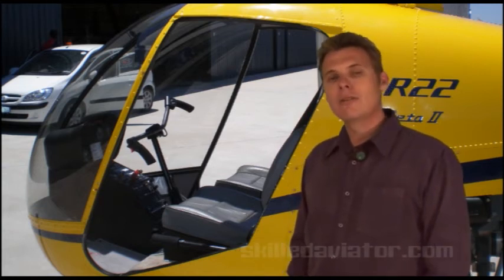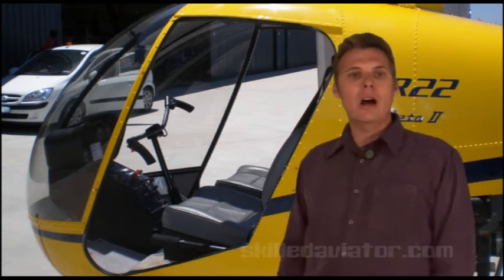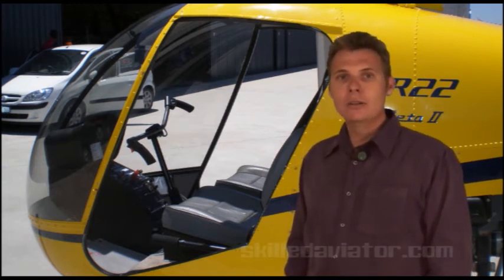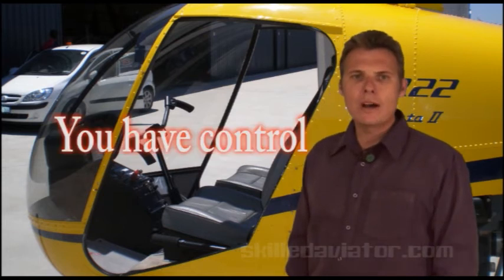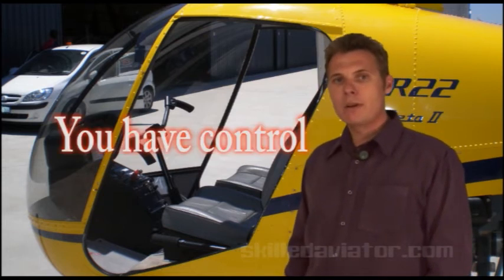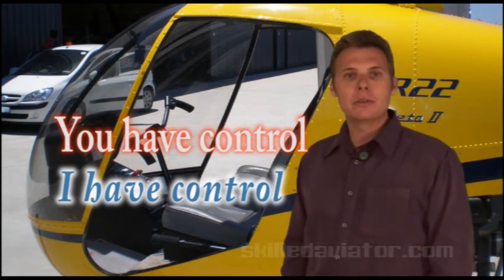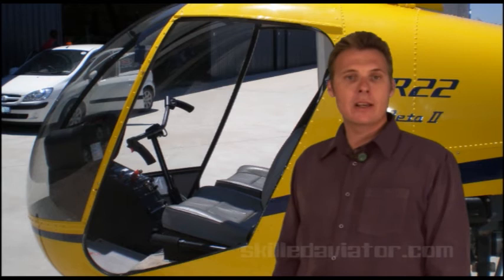When you are to be given control of the helicopter, your instructor will ask you to place your hands and feet on the controls. When you have done so, your instructor will say, "You have control." You must then repeat, "I have control." This must always be done to firmly establish who is flying the aircraft.